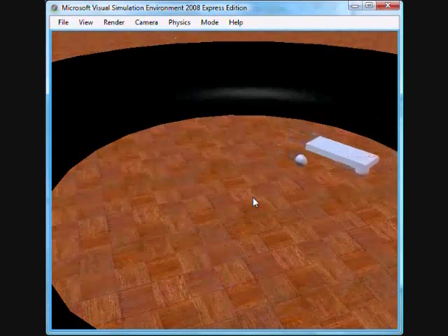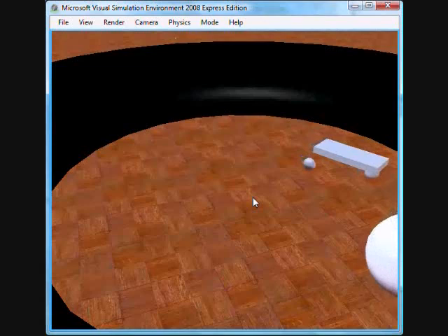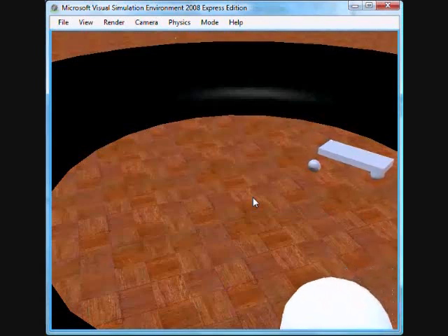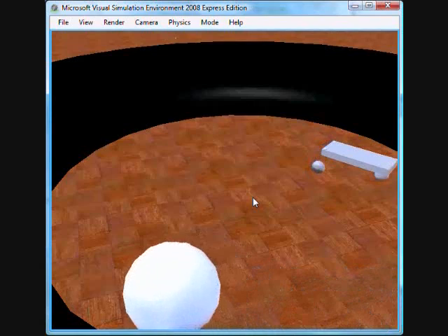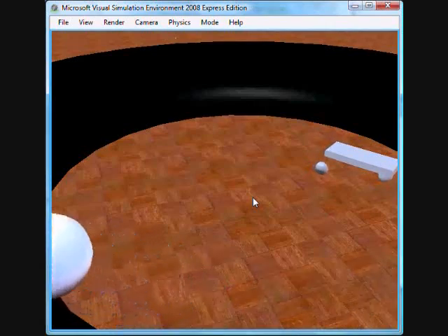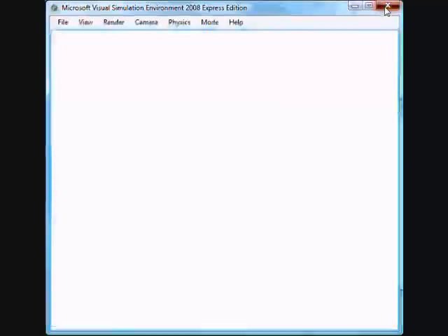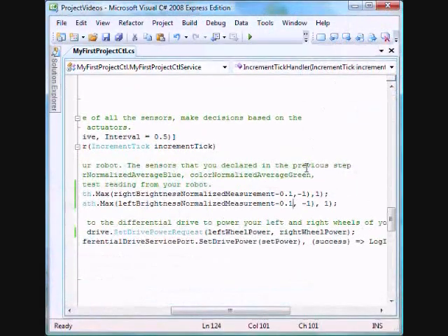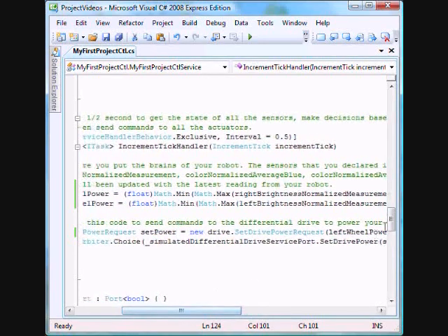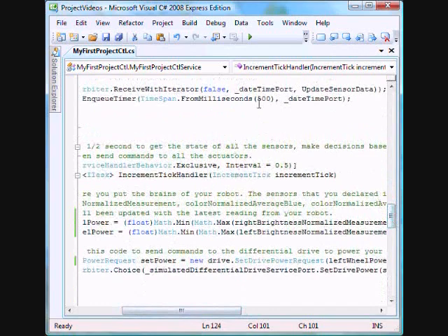This is because the sensors are read every half second. So the left sensor saw the ball, which drives the right wheel, and the right sensor didn't see the ball at all because the sampling rate is too small. Let's read the values from the sensors every 1/5 second instead of 1/2 second. Also, we'll send commands to the robot every 1/5 second. Let's run again.